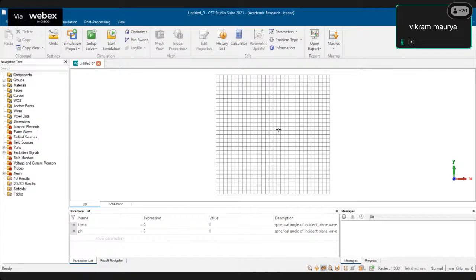It is not covering the complete ground plane, because I am not designing an absorber. I am just designing a metamaterial to prove that permittivity and permeability are negative. That's why the ground plane is not completely filled; it is a strip of rectangular patch only.